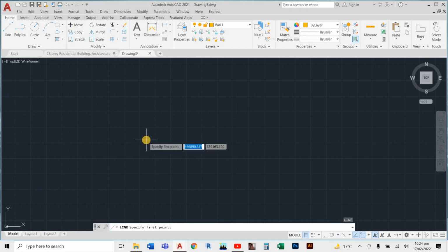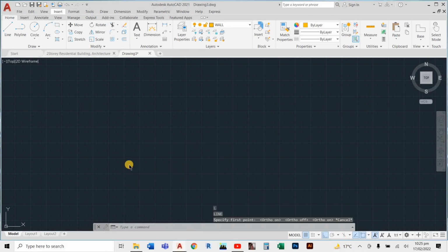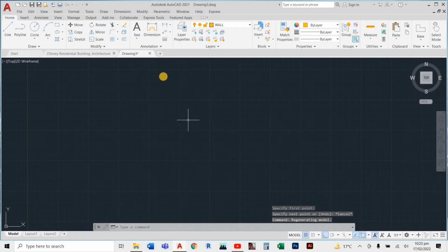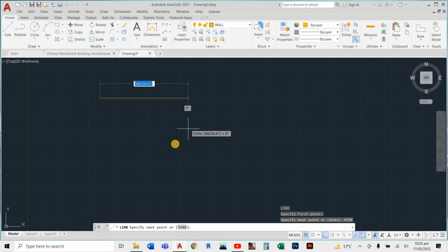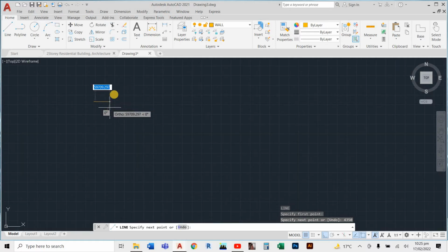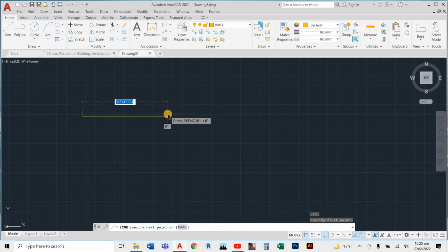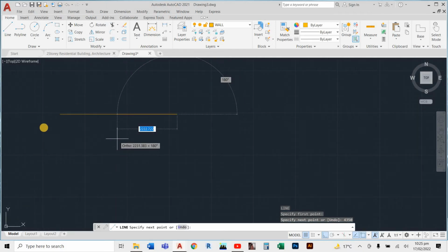So first of all, turn F8 on, then you can draw a line. Here we can draw by how much. For example, we get the dining room at 4350. It means 4 meters and 35 centimeters. Enter. Length of line 4350. Okay, this is our room.